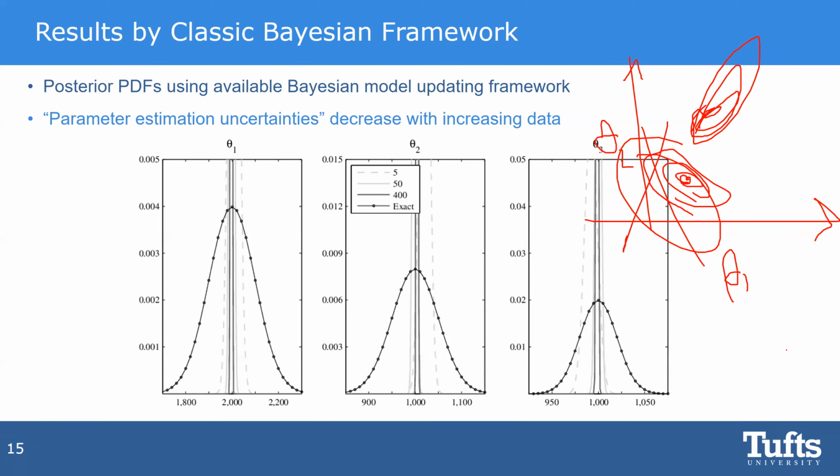When you want to establish a digital twin of a wind turbine or of a bridge or whatever, you have to take into account, among other things, your input space. This is very important. What operations of the structure have you considered in your data? Always extrapolating is not very good.